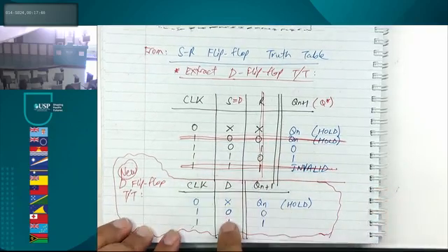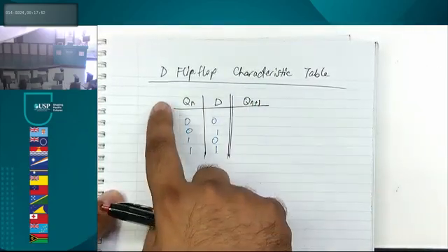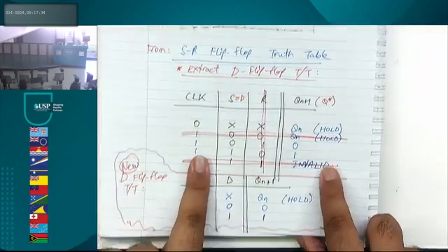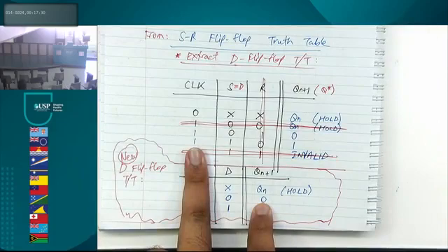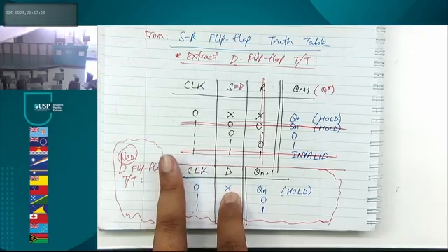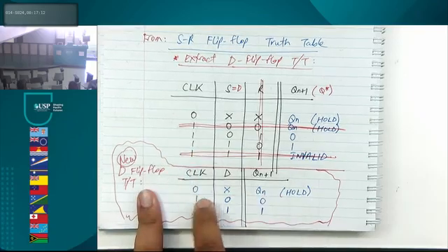All right. D0. Hey, guys, what can you say about the characteristic table? What's missing? Who's missing from the party? Right? Clock. There's no clock now. So we cover the clock up. D0, okay, D0 will give you a 0. But D could have also been a 0 here, and it would have given what? The current state. So current state was 0. So in both cases 0.